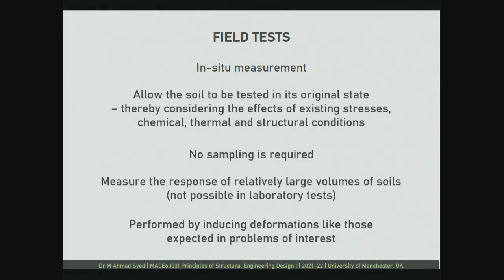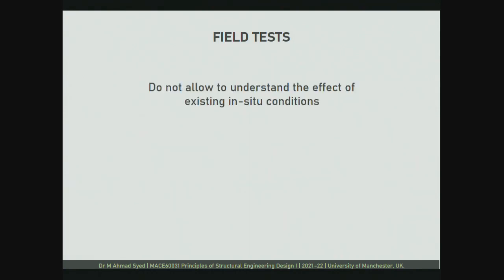Field tests, however, do not allow us to understand the effect of existing in situ conditions. We cannot vary those in situ conditions, unlike what we can do in the laboratory, where we can vary the test conditions. Also, pore water drainage cannot be significantly controlled. So that poses a challenge. Not all tests can be performed when we have pore water there.